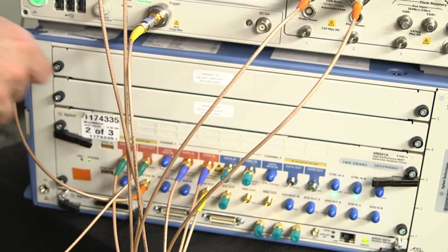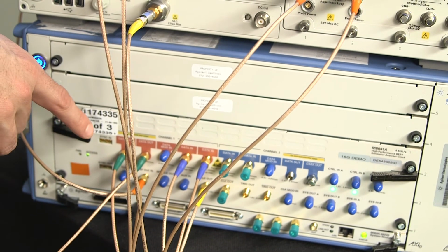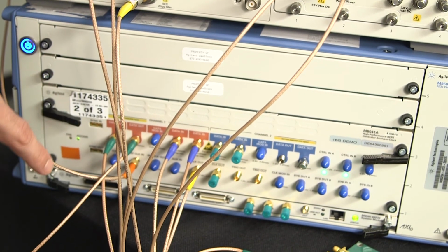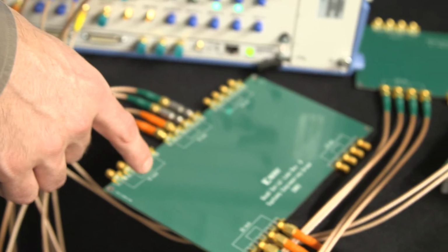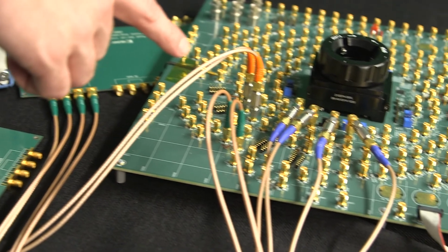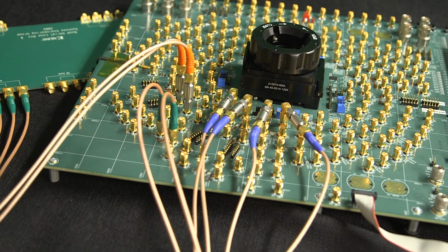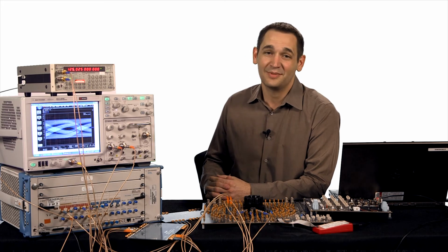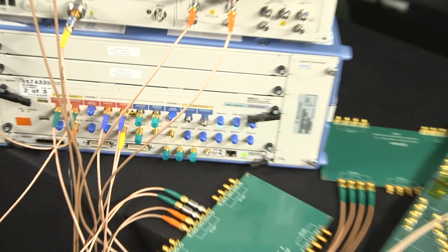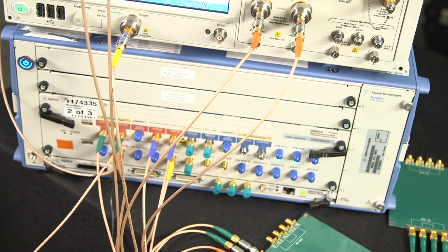The Keysight JBERT M8020A is set to generate a PRBS7 pattern at 1.25 gigabits per second. We then connect this to 85 inches of FR4. This is then connected to an UltraScale VU95 SelectIO receiver. The reference clock is shared between the FPGA's receiver and the JBERT. To introduce the plus or minus 100 ppm offset, we change the frequency of the reference clock to the receiver and keep the JBERT at 1.25 gigabits per second. The FPGA receiver clock is now running fast or slow compared to the data.